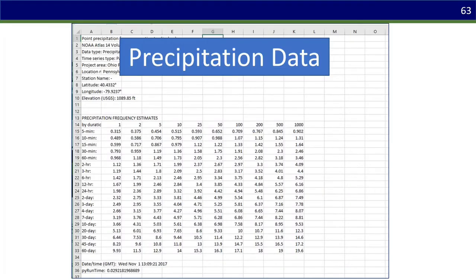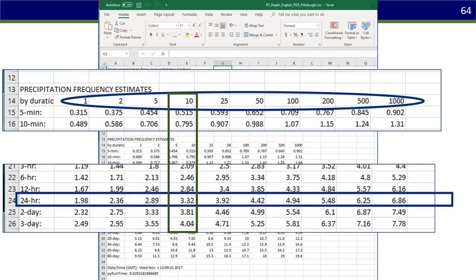So speaking of precipitation, here's a standard table. This is downloaded from NOAA, the National Weather Service, the Atlas 14 tables, for those of you who are familiar. It's a precipitation frequency estimate. We can look at the 1-year, the 5-year, the 10-year, and the 50-year estimates as we move across the table. If we zoom in, say, to the 10-year, 24-hour storm, the Cornell culvert model was built around the concept of the 24-hour storm, but we can use anything on this table.